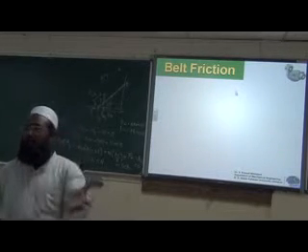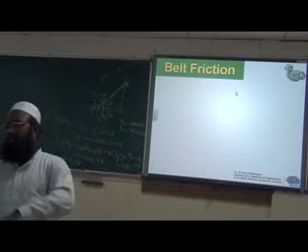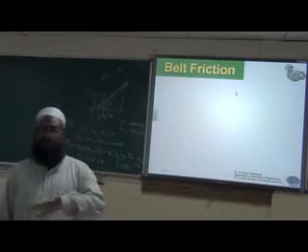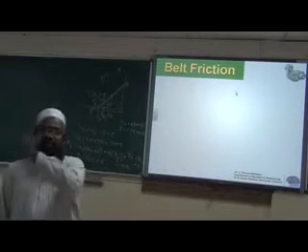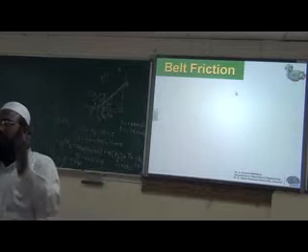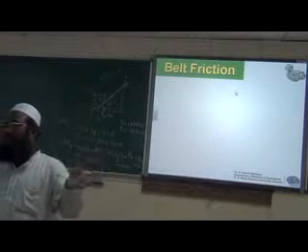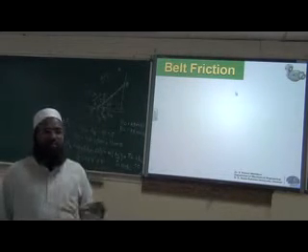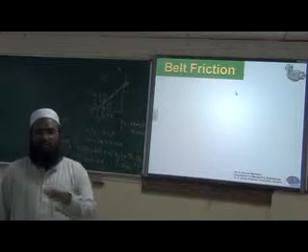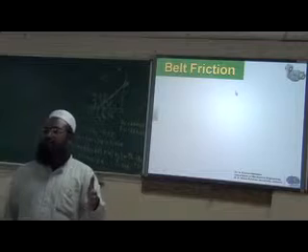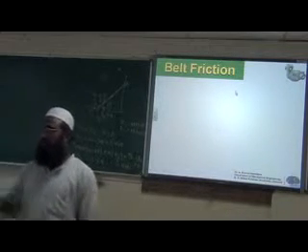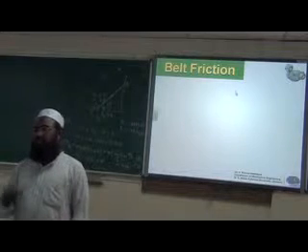It should be higher or it should be lesser. The speed may be increased or speed may be reduced. The motion may be at a 90-degree orientation. From the engine, we have to change the direction of rotation by 90 degrees. You have a propeller shaft, and the propeller shaft is connected to the differential. If you see the axle of the wheel and the propeller shaft, they are perpendicular to each other. So the transmission of motion takes place at a 90-degree angle.